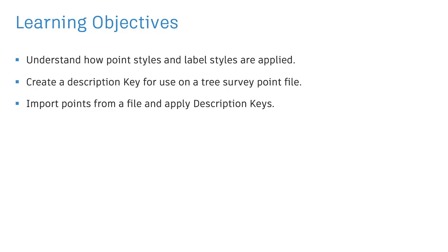Here you'll learn how point styles and label styles are applied to points. You'll learn about description keys and how they can be used to apply styles. We'll create a description key for use on tree survey points. We will import the points from a file and apply the description keys.